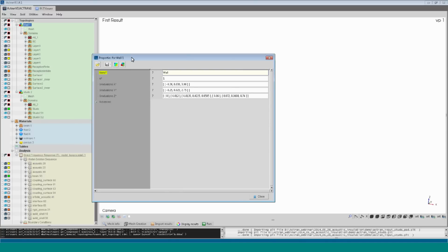So with the BoxPro tool, we first define all the regions that are covered by the different parts involved in the model. So along the X, Y, and Z direction, we will define the starting point, the ending point, and a step of graduation.